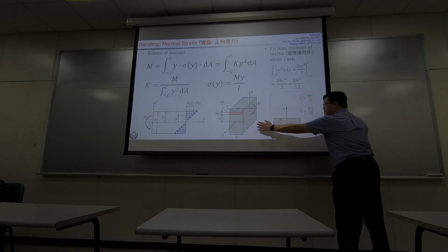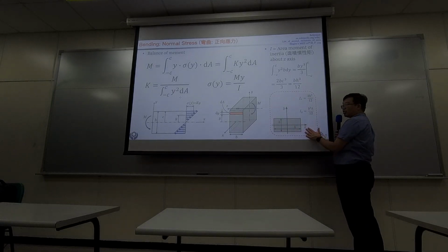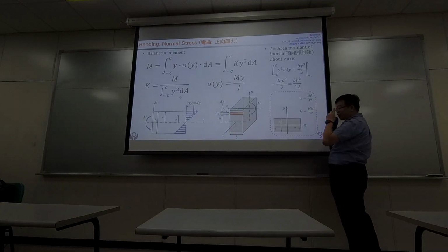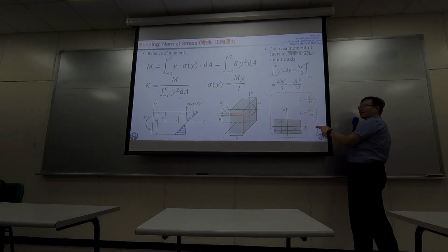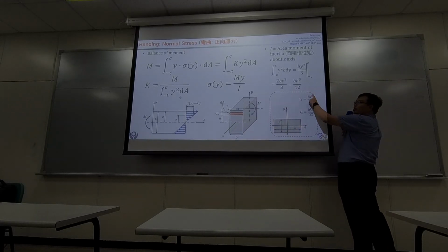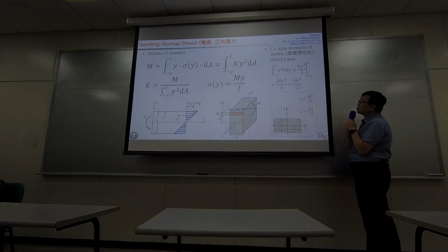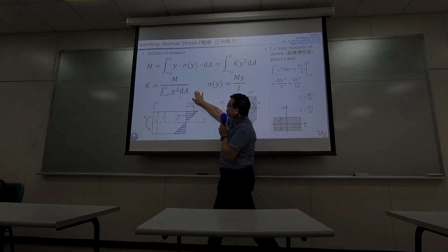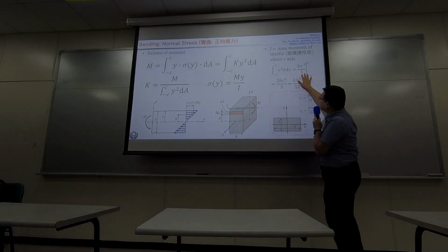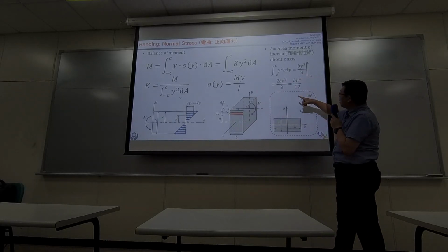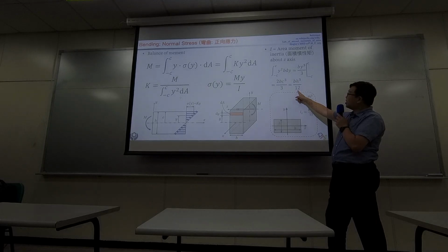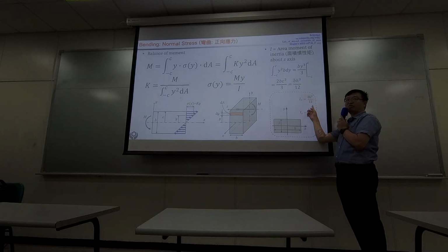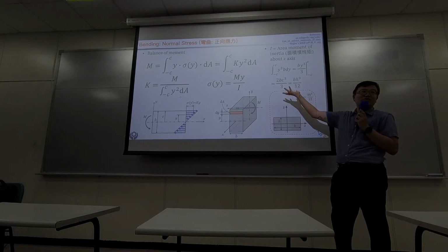So if you map it with the textbook, we should be checking the moment of inertia about the horizontal axis, which will be Ix. So we should be using this equation. Okay, so over here, there was a proof. If I compute this whole thing by the equation right here, just truly implementing everything, it ends up with this equation, BH cubed over 12. And from the textbook, same, BH cubed over 12. So in the future, you can use the textbook.